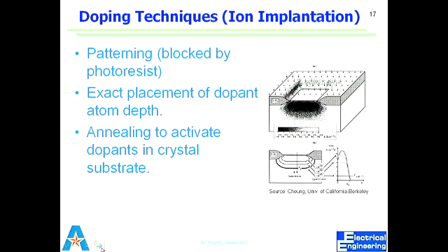So after both of the doping processes, we do a heat process in the absence of those gases to do what? It's called annealing. So why do we do annealing? To heal the damage to the silicon lattice and to activate the dopants. And activation means placing them in the exact place in the lattice, right?